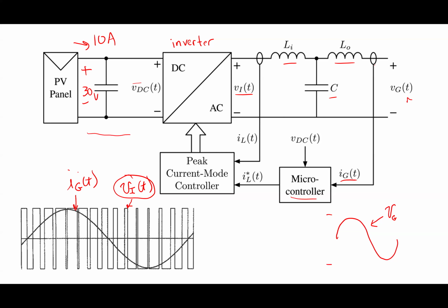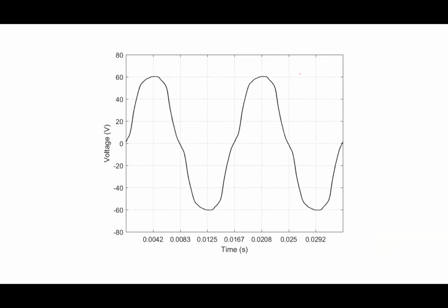But essentially it's a periodic waveform. And any periodic waveform can be thought of as having a set of harmonically related sine waves. What this filter does, what this L, C, and L does, is it basically removes all the high frequencies and leaves only the 60 hertz behind. That's the magic of how this thing works. So in order to design a system like this, if I want to design how it's going to operate, I need to understand the concepts of Fourier series to be able to do it.